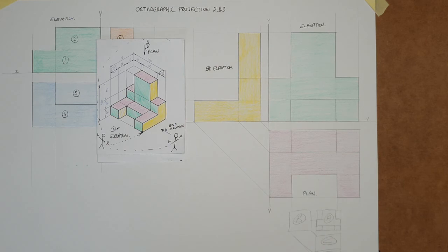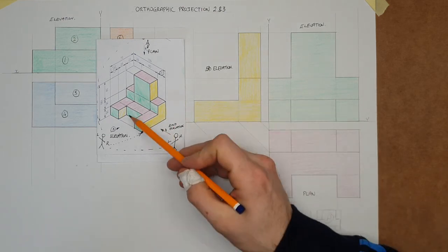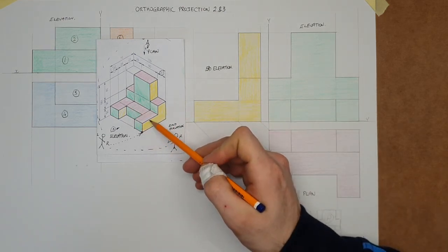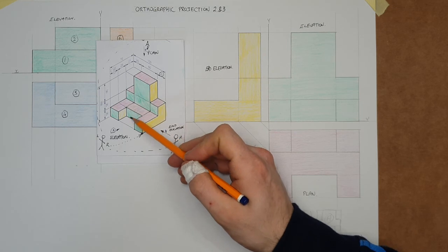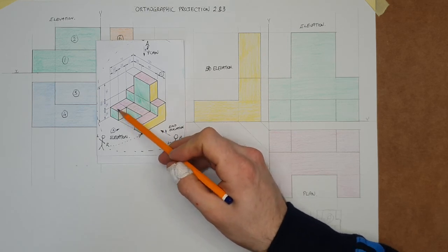The way we do that is called hidden detail. So something that is not evident on the surface, but that is happening in the background, we can show it as hidden detail or as a hidden line. In this case, there's a little bit more to it than that. It's not just quite as easy as just drawing the line, because first of all, we have to figure out where the line is. Now the line is going to be someplace back here.